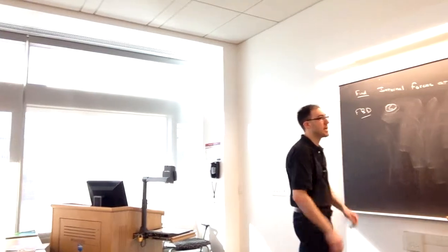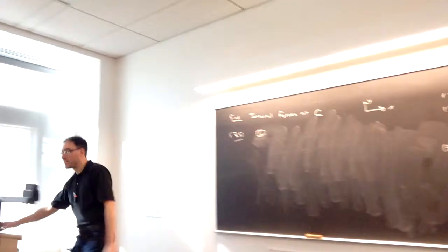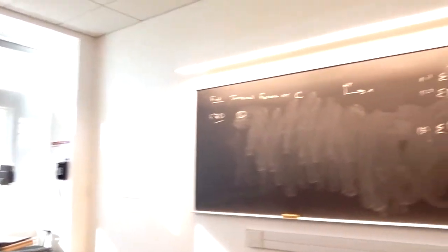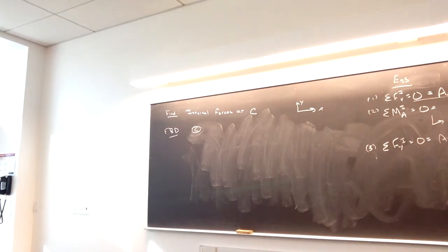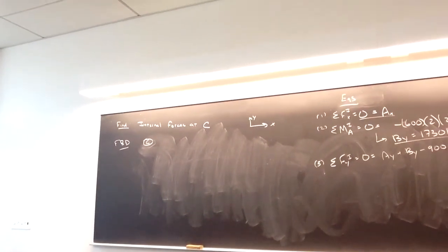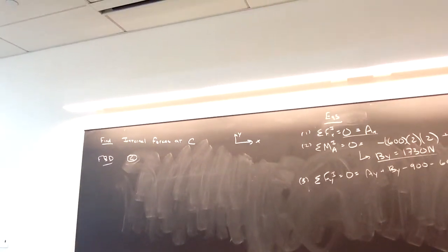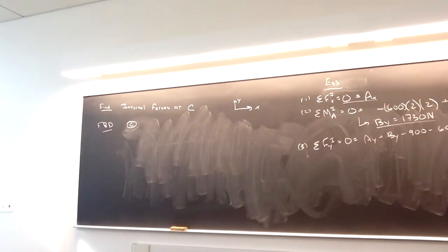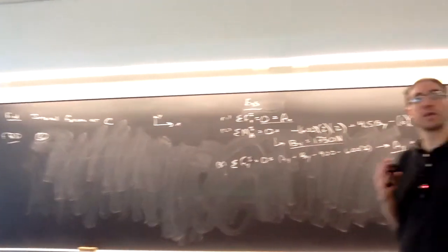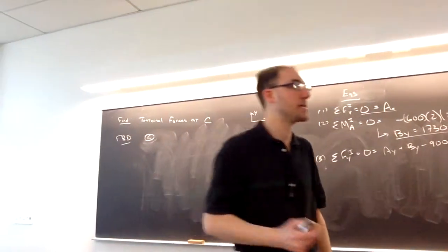All right, so jumping inside, this is where we make that internal cut at specifically C. And specifically, we want a vertical cut that passes through there. So remember from 211, when we make that cut, we have the option in our picture. We can take everything to the left side of the cut, so that includes what's happening at A, or everything to the right side of the cut, so that's including what's happening at B and the applied force at D. We're going to get the same answer, the same magnitude of answers at least, either way.